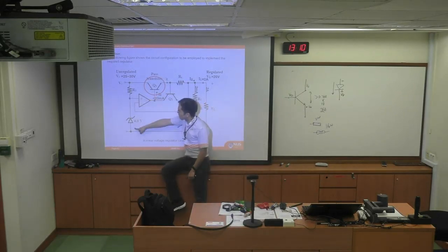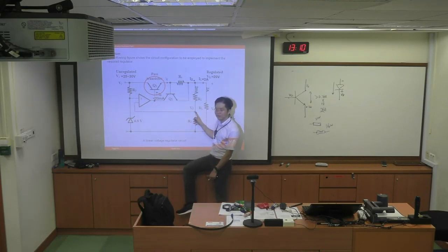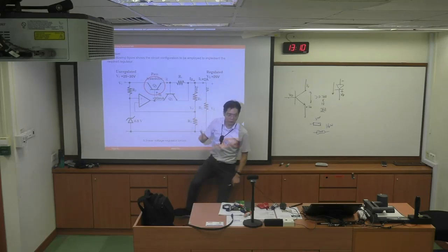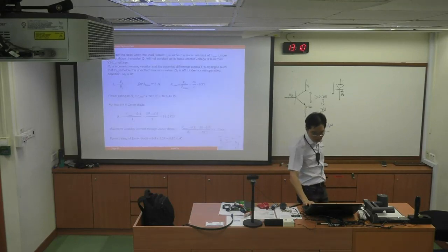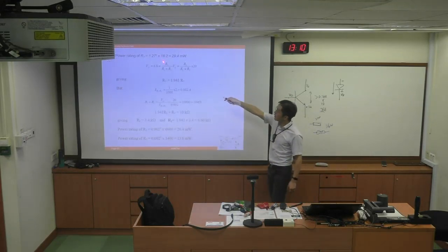This is 6.8 volts. The plus and minus ports have the same voltage, no potential difference, so it should be 6.8. Your target VF should be 6.8 consequently. So these two voltage divider resistors should give a VF of 6.8 out of the 20 volt output. So you have one equation with two variables, R1 and R2, with 20 multiplied through yielding 6.8.